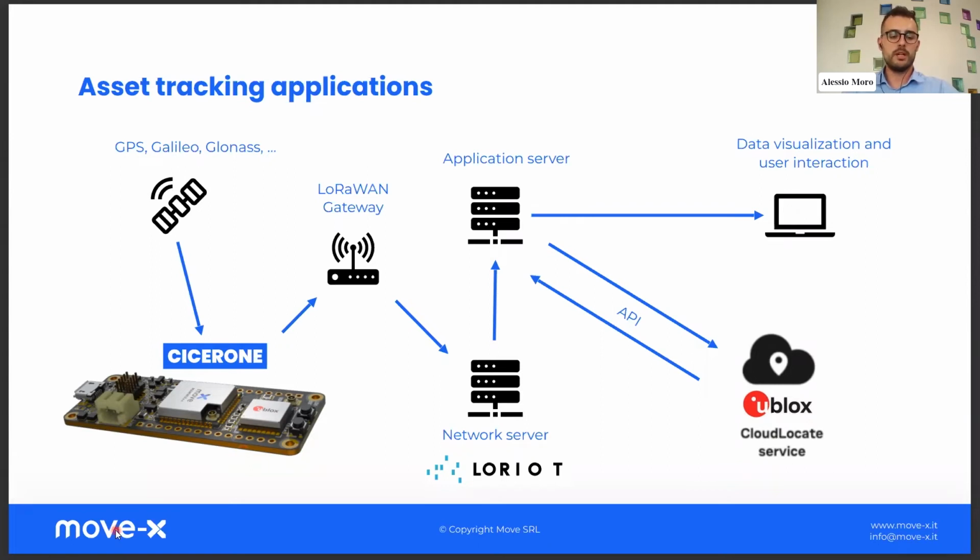Both modules are optimized for low power, and this low power consumption is matched by the possibility to power the board through a battery. The board also has a battery management circuit that makes it possible to recharge batteries connected through the connector. Compatible batteries are LiPo 1 cell, usually 3.7 volts, and the size of the battery can be dimensioned based on the application.